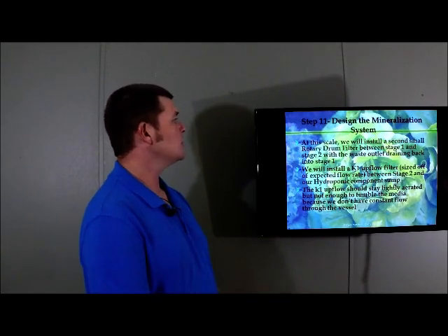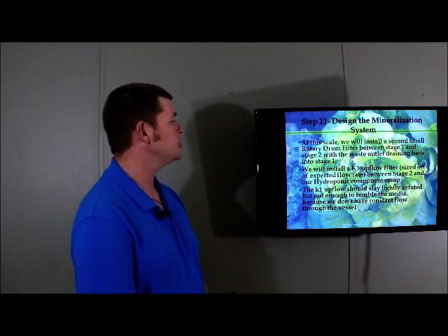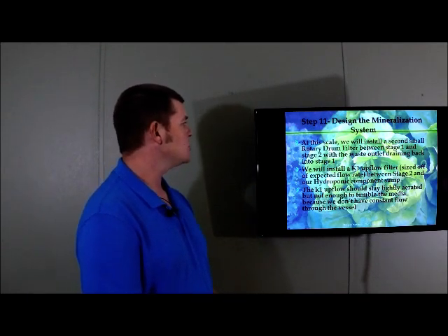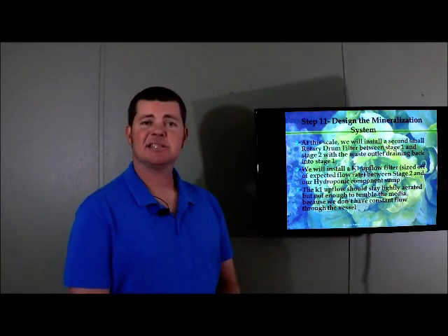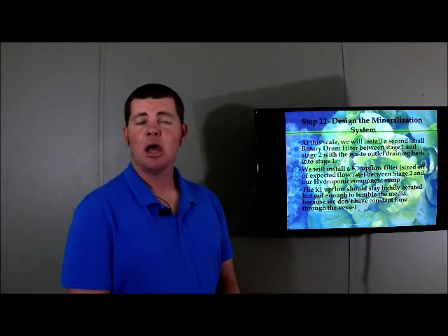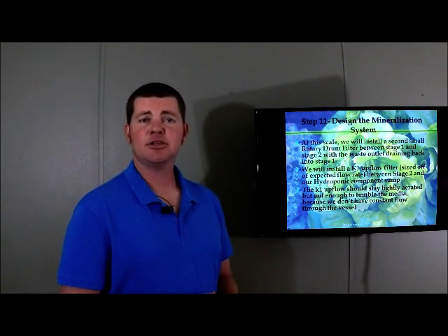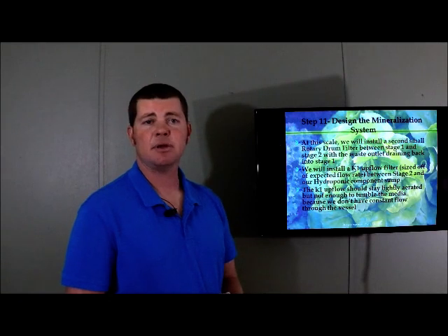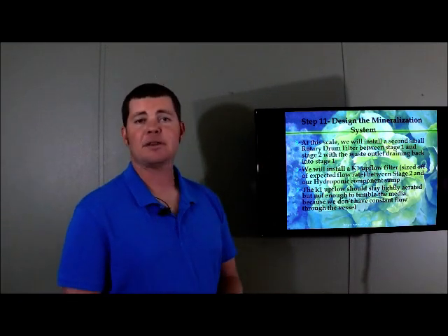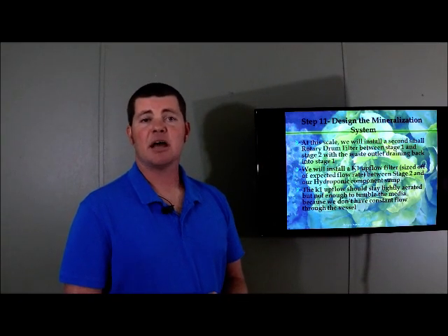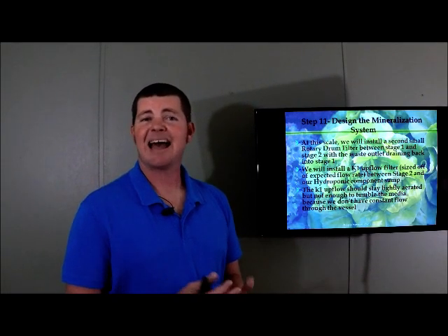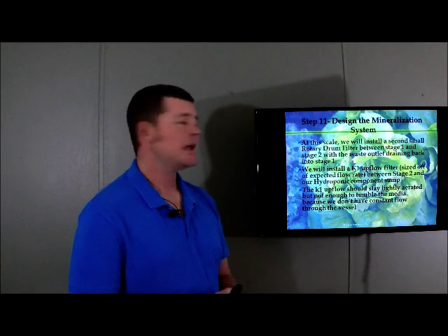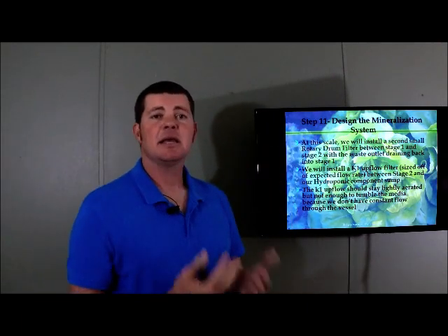At this scale, we will install a second small rotary drum filter between stage 1 and stage 2 with the waste outlet draining back into the stage 1 mineralization tank. Okay, so at this stage, that is not a huge cost to throw into the entire cost of the build. It might be a $3,000 or $4,000 drum filter, and we're talking about a $500,000 to $750,000 project. That's not a huge percentage of the cost, okay? So that would make sense in this scenario.